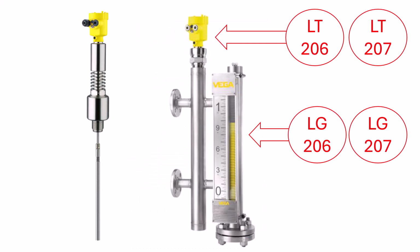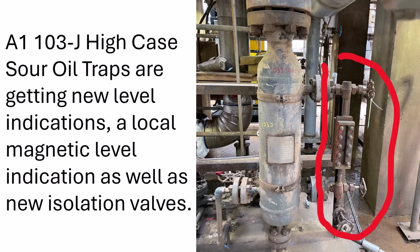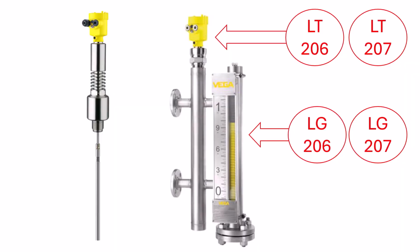This new level element will be installed in a separate column, not inside the seal oil trap, so it will be easier to maintain. To accomplish this change, we are going to remove the local site glass column. We will also demo the physical pieces at the top of the seal oil trap. These are part of the old float level indication, and a spool piece will be installed here on both high-case seal oil traps. Replacing the old site glass will be this new dual column setup, with the level transmitter and a local Magtech style indication.